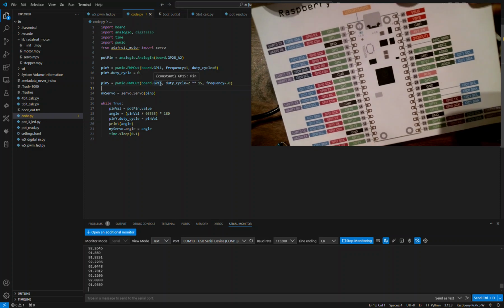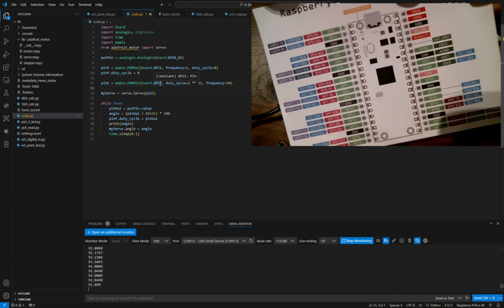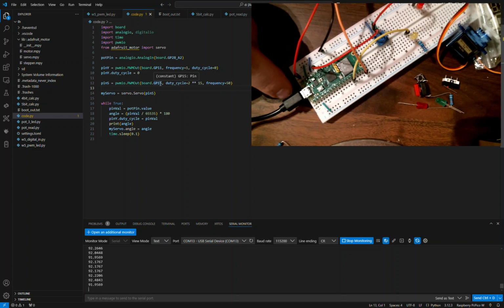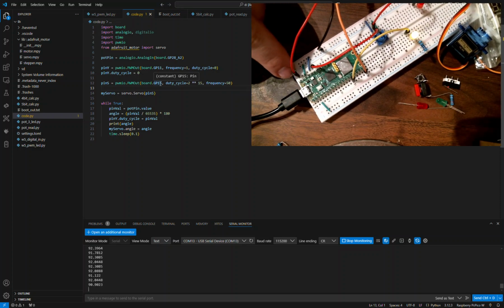We're going to use this V-bus. The V-bus is 5 volts. It's the direct line of the 5 volts coming out of the USB port, and it just comes right out of this first pin.